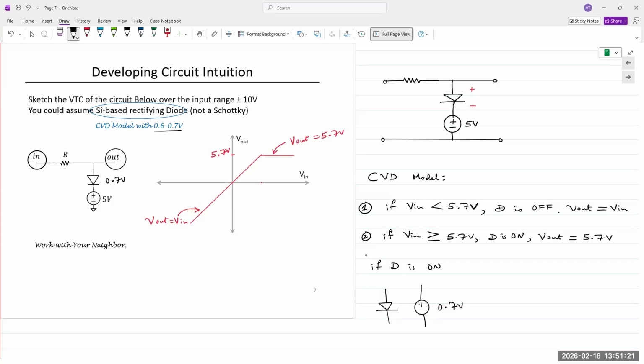And since the anode is positive, the positive terminal of the source is where the anode is connected. So when we have replaced the diode with a voltage of 0.7 volts, that 0.7 volts is in series with the other 5. And that's why they're added up. Does that make sense? Does that answer your question? That's why it is 5 plus 0.7.